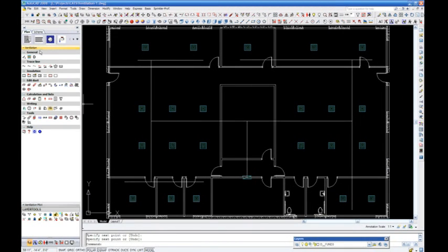Once our center line is completed, under the C.A.T.S commander under Ventilation, select under Trace Line. Repair Trace Line Global. After selecting the center line, we are creating a trace line. Now we are connecting our diffusers automatically to our trace line. In the AutoCAD command, we are asked to select the diffuser. In this case, we select all diffusers.